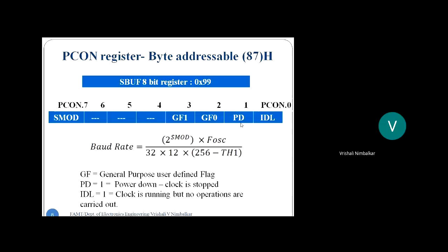Now, to come out of power down mode, we compulsorily need to reset the microcontroller. And once we reset the microcontroller, you all know what the states of the SFR registers are on reset. Right? So to come out of the power down mode, we need to reset, and hence the majority of the special function registers are cleared. All the ports will have logic 1. The program counter is also cleared. The stack pointer is initialized to 7. Meaning the SFR registers change.